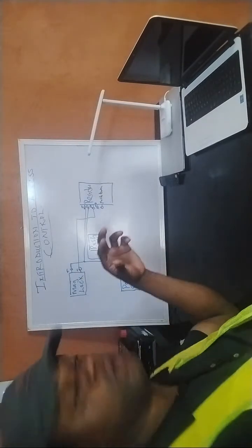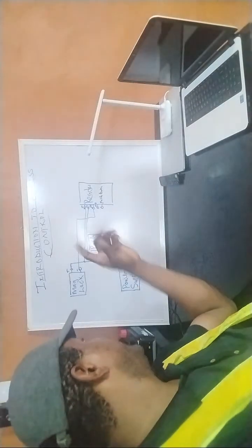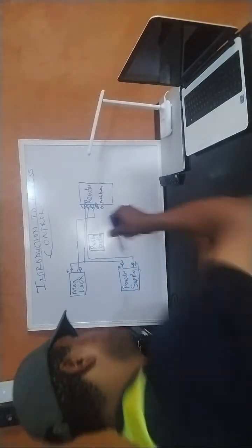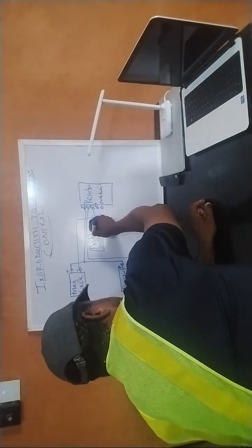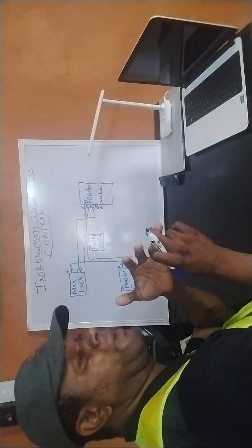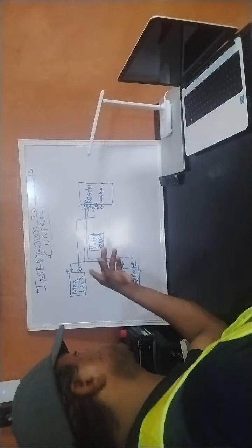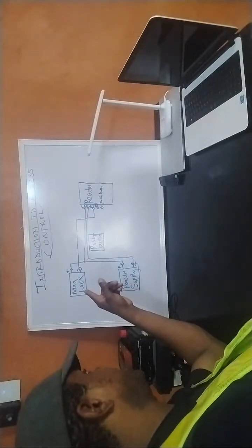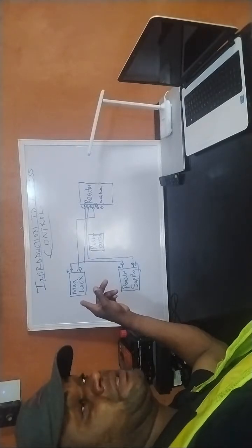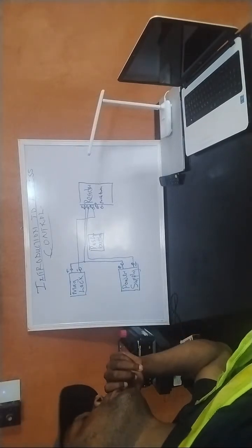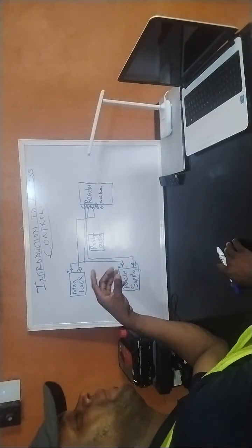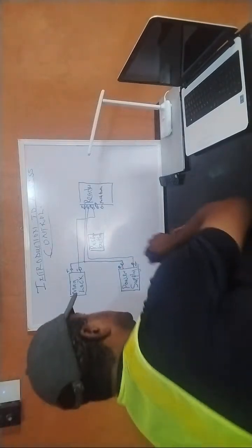All right. So another thing you should be looking for is this push button. Where do I get it? Because on your push button, you have two terminals. Sorry, there are three. Some are normally open and some are normally closed. We're using a magnetic lock, so for my push button I'll use the normally open for this.